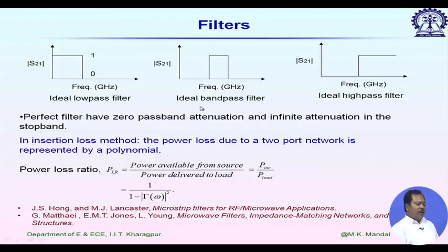For example, if we have to design a band pass filter, then in band, or in the pass band, it will have good impedance matching with the source and load, and out of band the impedance mismatch will be as high as possible. It is done by changing the S parameters of the component we use for filter design.